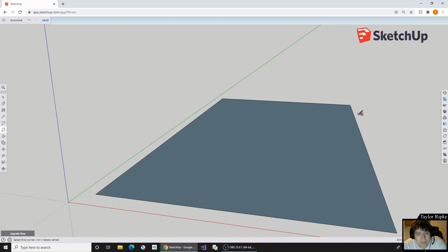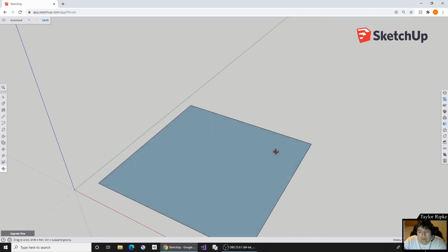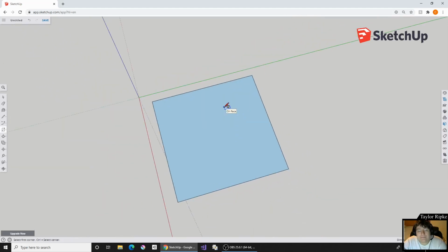Now, what's a really helpful tip is once you click, drag, and release to create this rectangle, you can actually enter in exact dimensions. If you look at the very lower right-hand corner of our screen down here, you see dimensions. It tells you exactly that this is 21 feet by 10 and an 1/8 inch by 39 feet, 2 and a 16th inch. We can actually type in different dimensions. So let's say we wanted to do 15, and then the feet symbol is a single apostrophe, so 15 feet, comma, 15 feet, and press enter. That's going to resize the last geometry that you manipulated. So we just manipulated that box. Now we entered some exact dimensions, and it's going to be a perfect square.